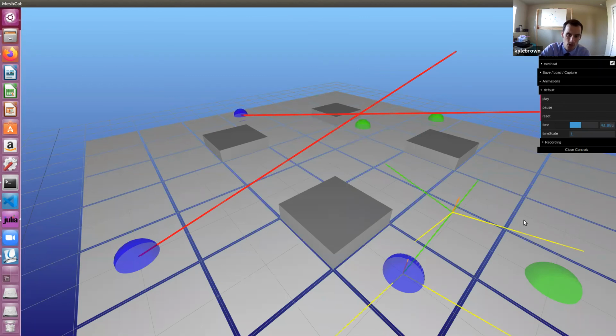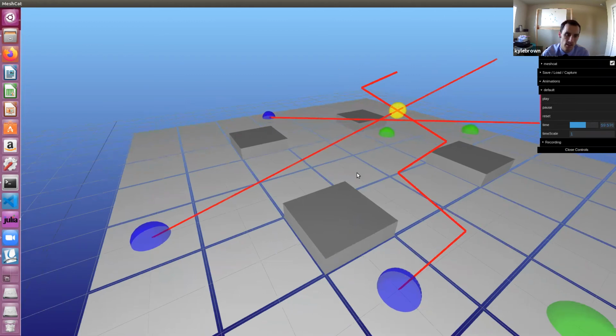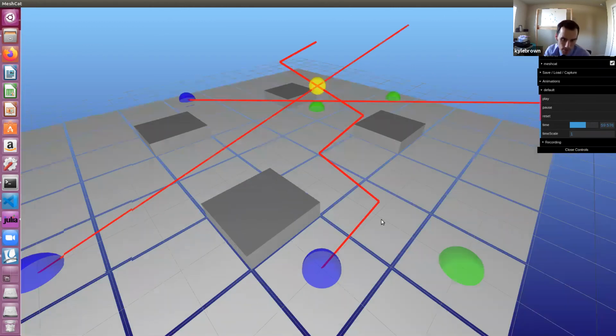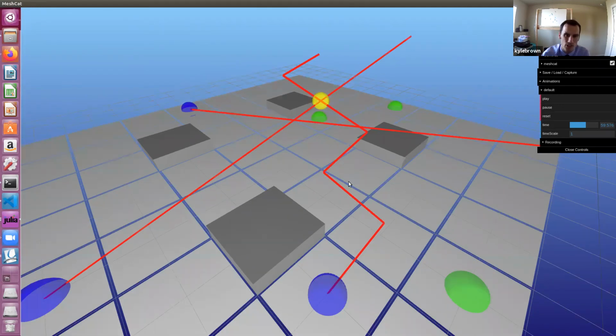You'll see that when the search tree encounters a collision, it will try to find an alternate path that doesn't have a collision, but still reaches the goal in minimum time. So you'll see now at the end of this search that we recover a different path, which is a little bit better because it only has 1 collision rather than 2 collisions like the first one. So here our tie-breaking collision cost function has come in handy, but we still have a collision.